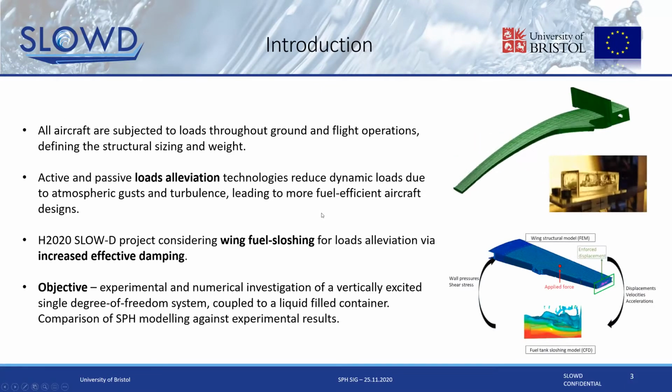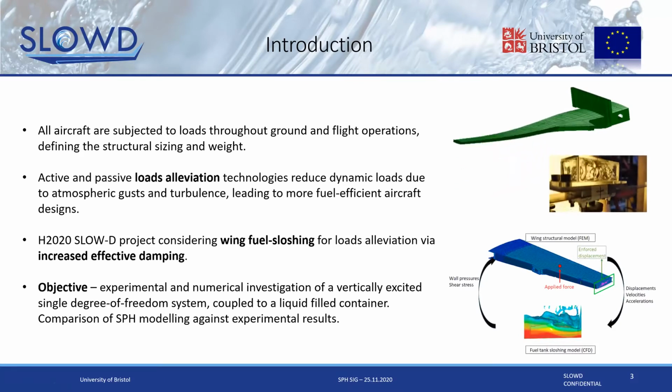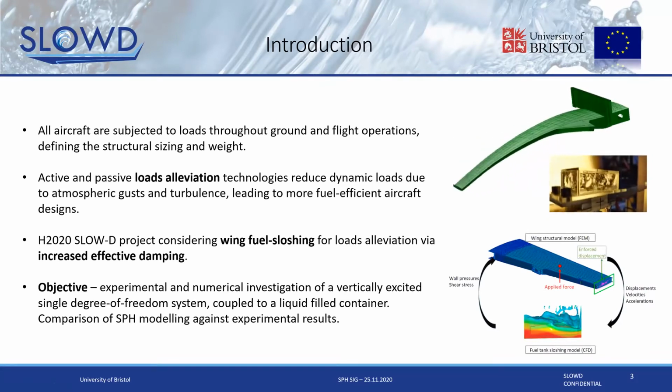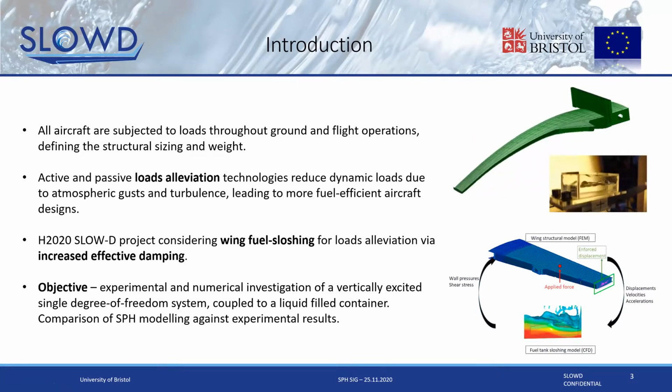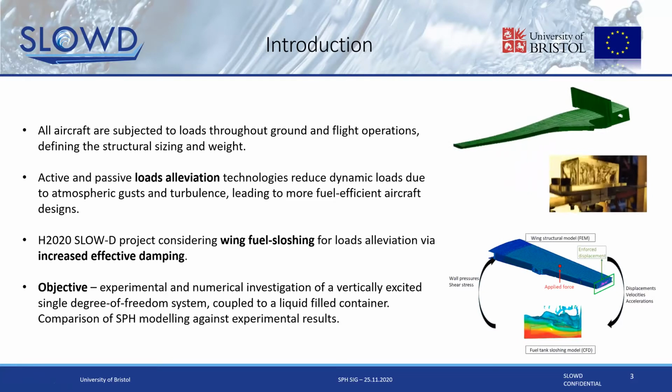Okay, so if we imagine there isn't a global pandemic and we're actually getting to go on holiday somewhere nice, and we're flying along in our aircraft and we undergo some turbulence, you look out the window and you'll see your wing shaking as well. And within your wing, that's where your fuel's stored. So as we undergo this turbulence and gust loading, all that fuel inside your wing is also sloshing about, and it's actually absorbing and dissipating energy, and damping out the motion of the wing.